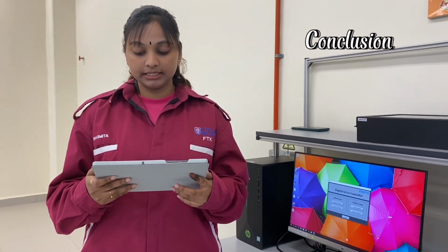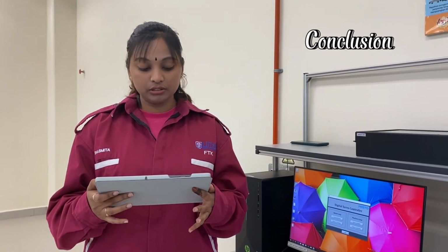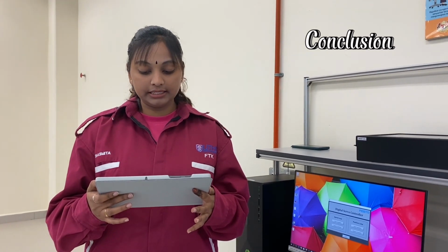As a conclusion, from this experiment, we familiarized ourselves with servo system operation in closed loop speed control. We also learned how to calculate and measure the steady state speed of the digital servo in closed loop speed control. Then we also learned to calculate the error value between the reference speed and the actual speed, and how to minimize it by increasing the controller gain.